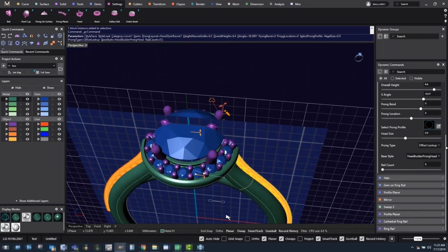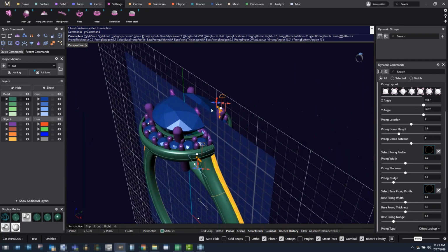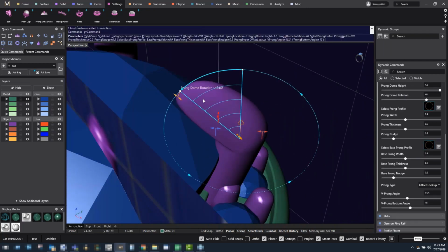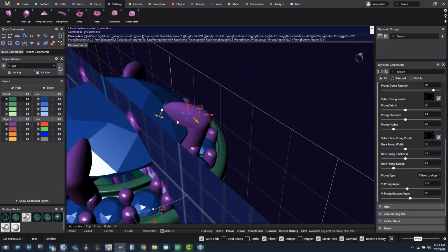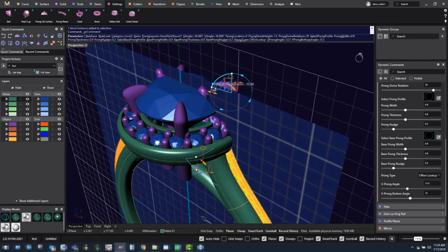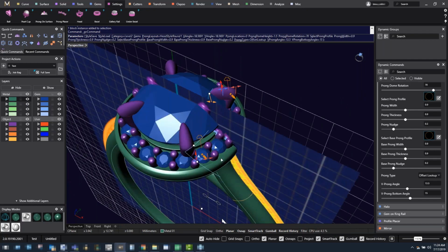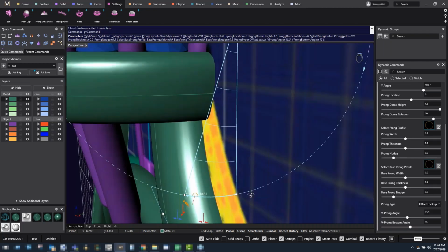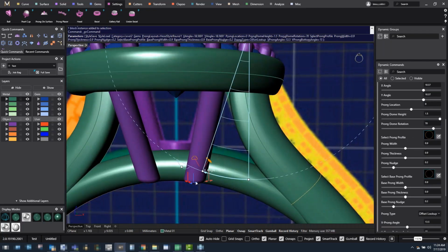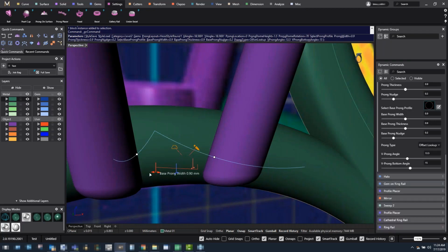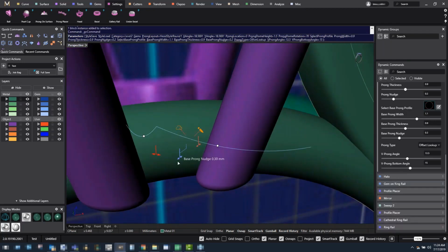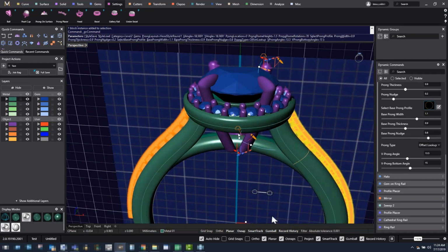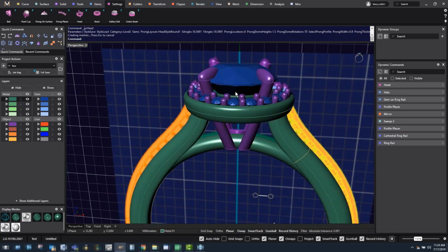So let's go to level 2. So here for the first time in Gem Vision software, you can produce a set look. So I'm going to extrude the dome and then angle it over my stone, and it gives you that nice kind of set look. And it also opens up some more viewport handles, right? So you can come here and further adjust. I'm going to pull the base nudge in a bit, and that'll kind of give that pull to point look. So let's right click, accept.